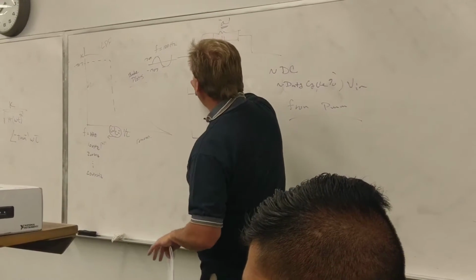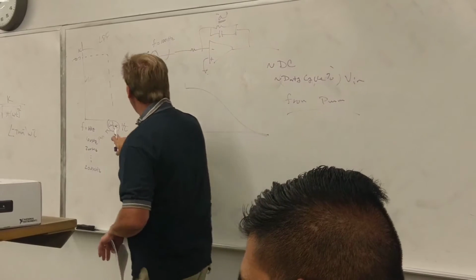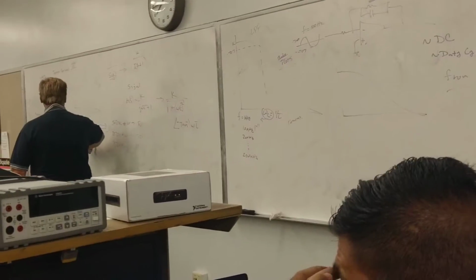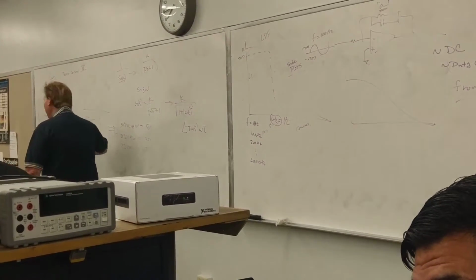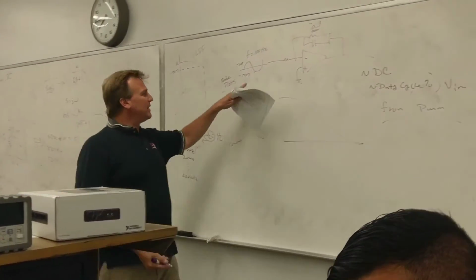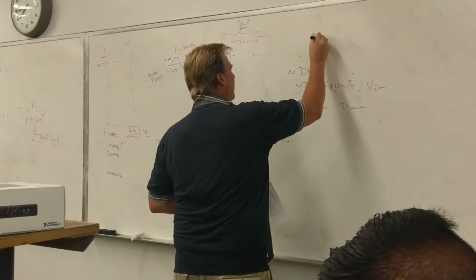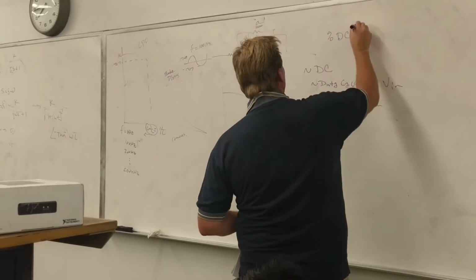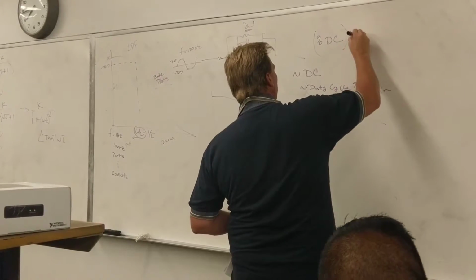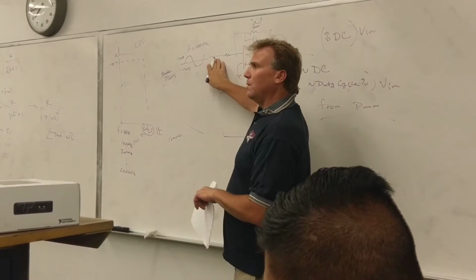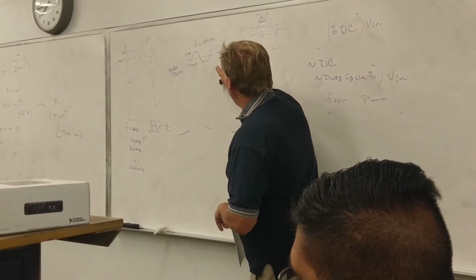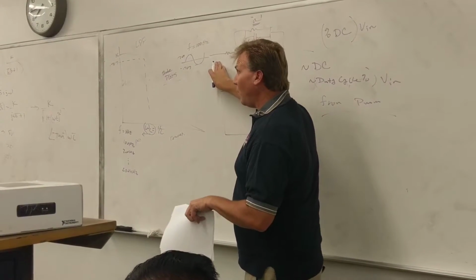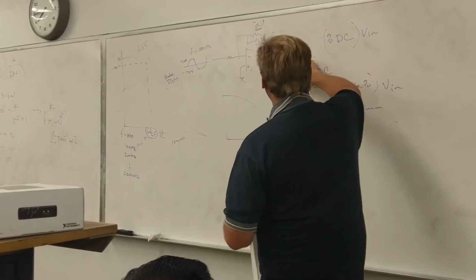Part 3, once we have a pretty good cutoff frequency, so you know where this needs to be, then you're going to set your PWM frequency here, and you're going to vary the duty cycle, such that the duty cycle will come out across here, as we would see the duty cycle over here times the input to this guy right here. So in part 3, apply the LabVIEW signal that you generated in part 1 to the filter, and get the duty cycle out.